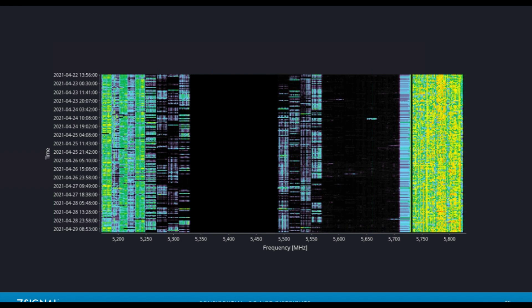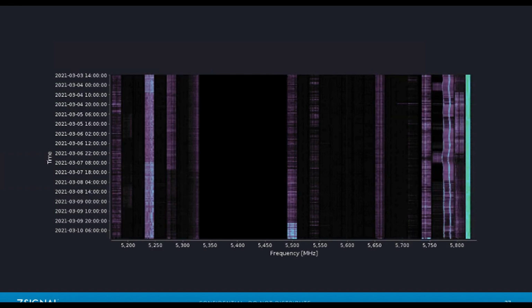Yes, they were. And then our final slide right here is a really interesting one. You see this little wiggle worm right here, Jim, this little sliver, top to bottom. Now, we were able to work with the customer in order to trace this down. This is very abnormal, so it looks very different than everything that we've seen so far. This is a motion sensor. And this motion sensor just continually broadcasts, transmitting as it tries to detect motion, but basically renders this channel useless for Wi-Fi.